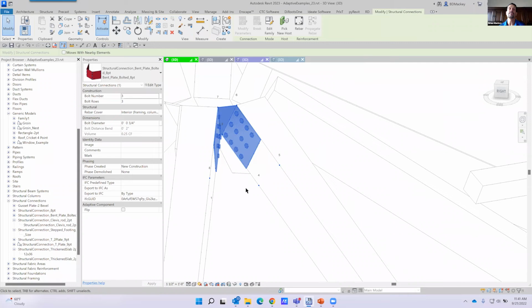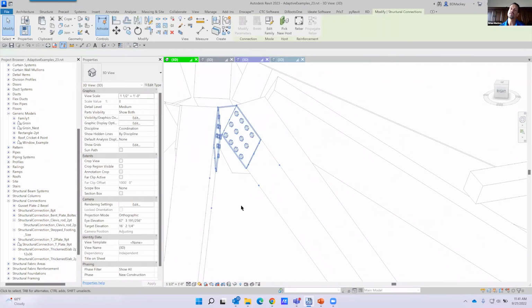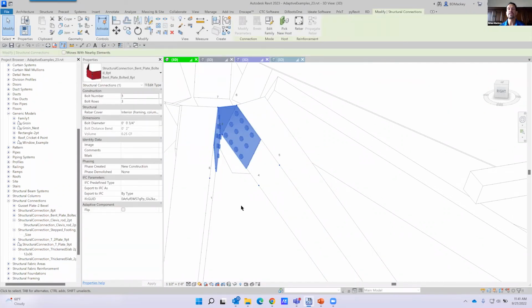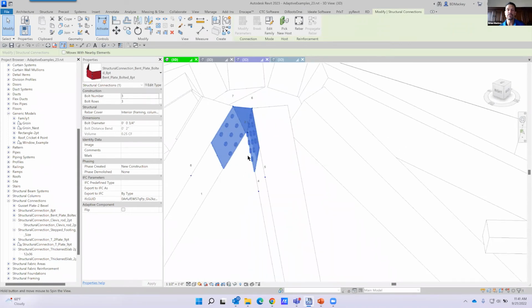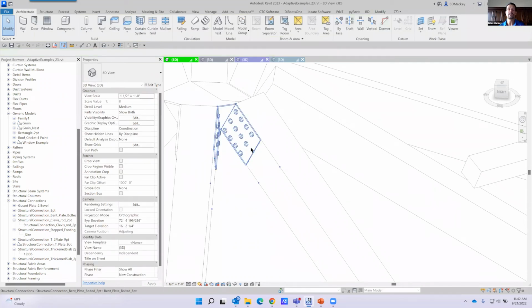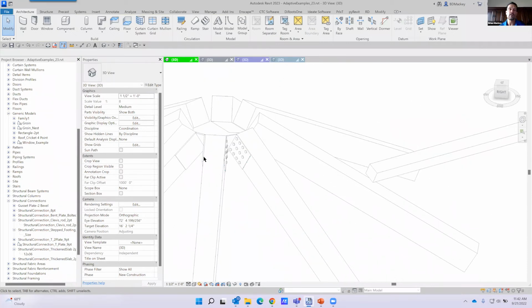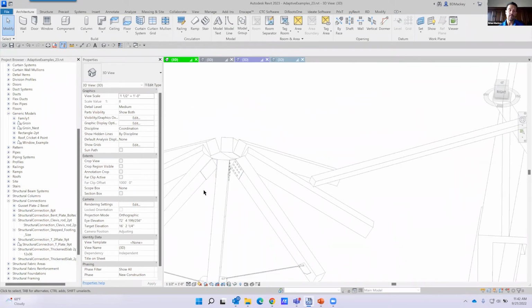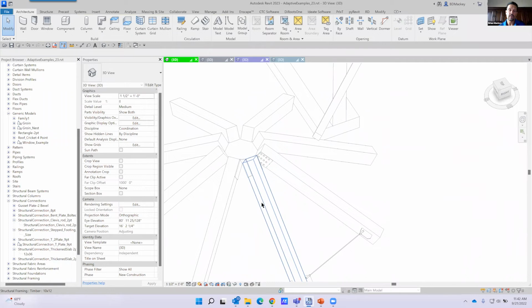Yeah, putting too many of these in, I've noticed the project goes slow. So when you start looking at something like this, it's really cool to see all those bolt heads. It's technically not even a bolt, it's just the bolt head. It looks great, but since it's 2 nests into here, these are the things I've started to see slow it down. The adaptive component families themselves just put in here, no, I don't notice any sort of slowing down on something like that.